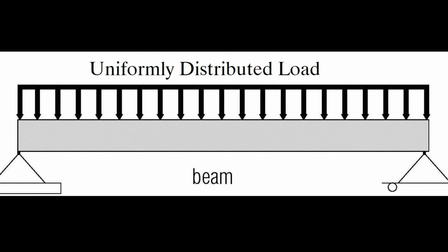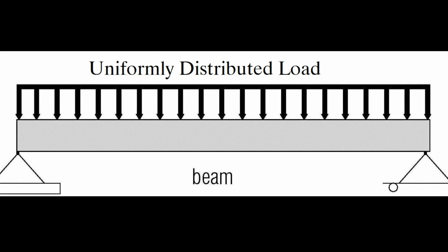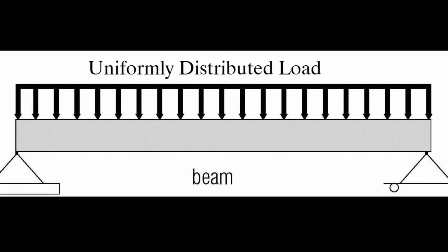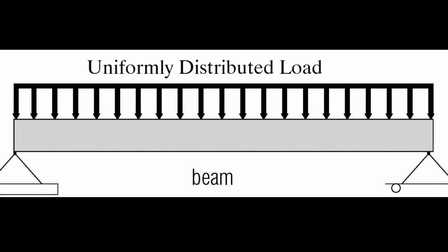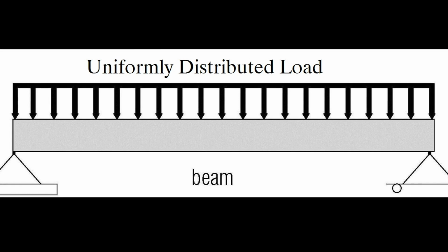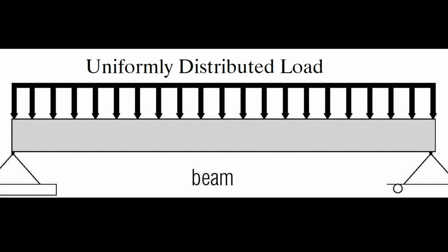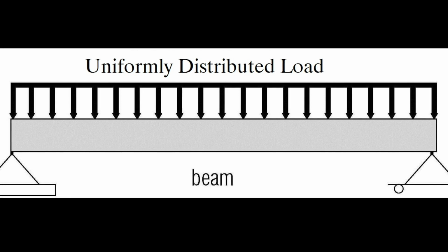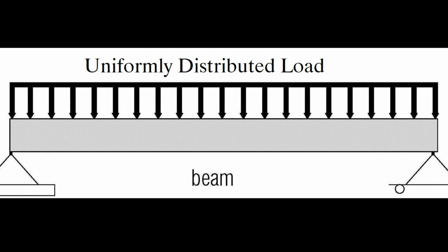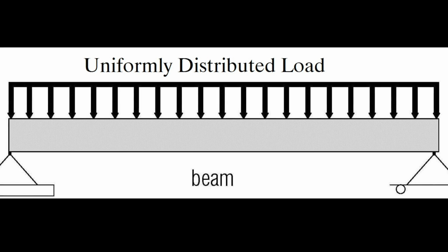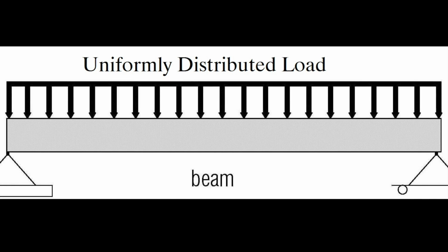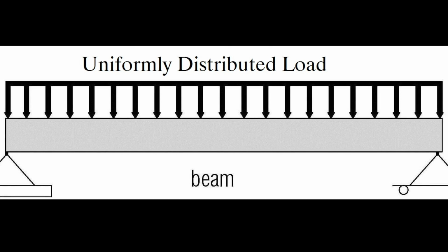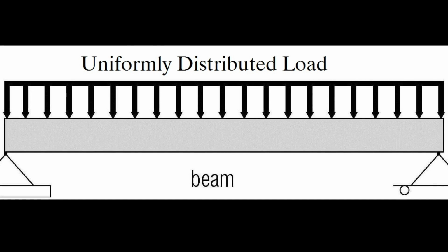This was used to find the reaction force of the middle column, which was 695.14 kilonewtons. This was given by a teacher, since it helped us identify the reaction forces for the small section of the bridge, 5.7 meters, and the large section of our bridge, 10.7 meters. To find these, we had to divide the load acting on the bridge by 2, which gave us a value of